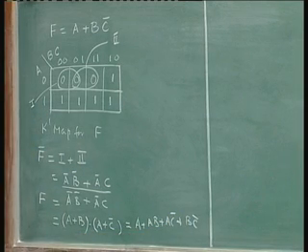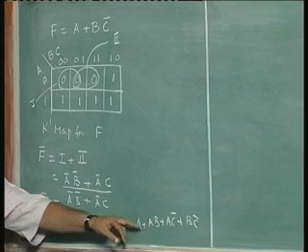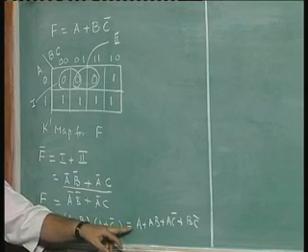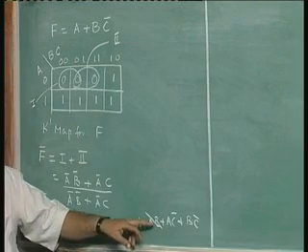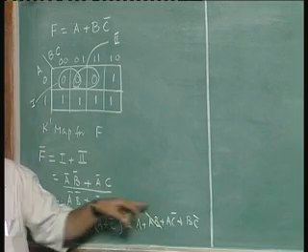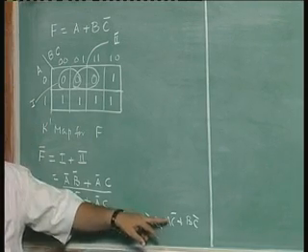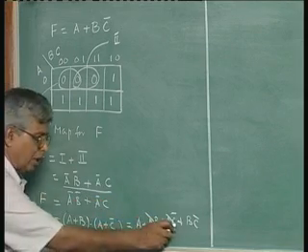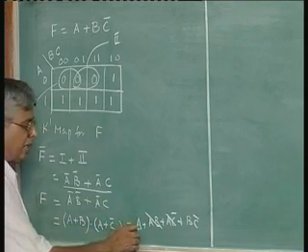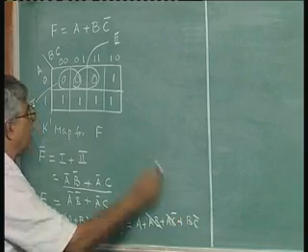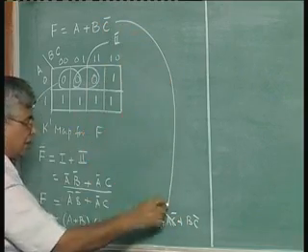We have the identity in Boolean algebra, if you remember, A or AB is A, correct? So this is redundant. Similarly, A or A bar, AC bar is also A, this combined with this will give you A. So, these two terms get knocked off. So, the result is A plus BC bar, which is what this is.